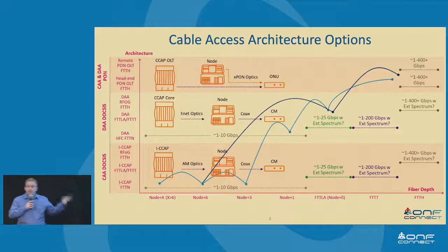Or you can fiber overlash and go down and split that cascade quite easily, right? And so you've got a lot of flexibility now in how you treat those customers. And as you do that, you're effectively adding more and more bandwidth to the mix. But also, you're lowering a lot of the noise contribution and artifacts that are in the RF system.